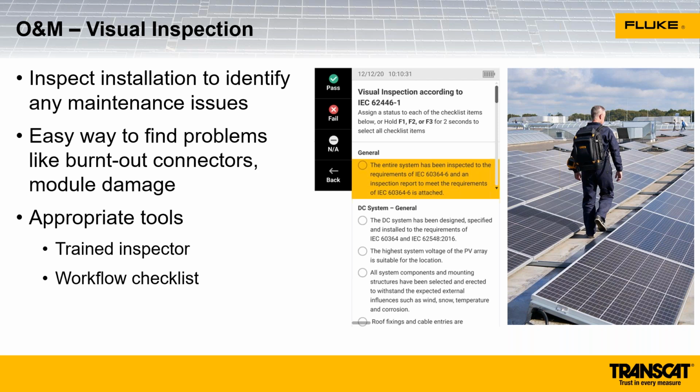This checklist on the screen here is in our SMFT 1000. That's based on the IEC 62446-1 standard. And having a trained inspector is really important. They need to know what they're looking for, when signs of damage have occurred, and when to flag that for future inspection and root cause analysis.